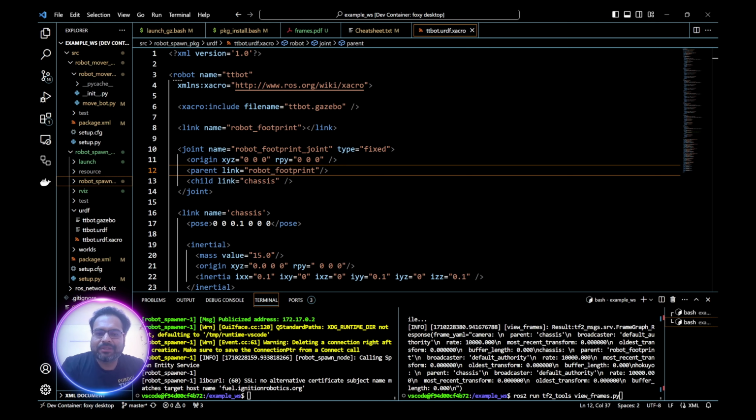Then there are inertial properties of components, such as center of mass and inertia, which are link properties for each of the links. They're crucial for simulating the dynamics of the robot, because the simulator that we're using, especially Gazebo, is a physics-based simulator. So you have properties like mass and inertia. Then there are also visual and collision representations, because each link has some sort of visual representation, and collision describes the collision detection during the simulation.